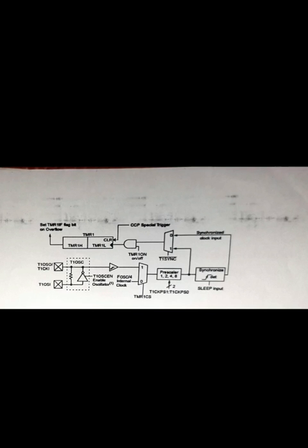This register holds the lower 8 bits of the timer value. TMR1H and TMR1L are used as a pair to increment up to FFFFH. PIR1. This register contains the timer 1 overflow flag. PIE1. This register contains the timer 1 interrupt enable flag.